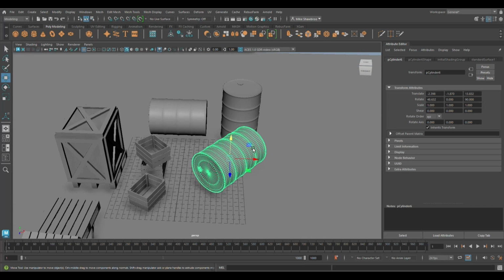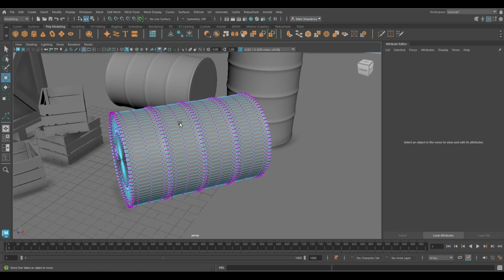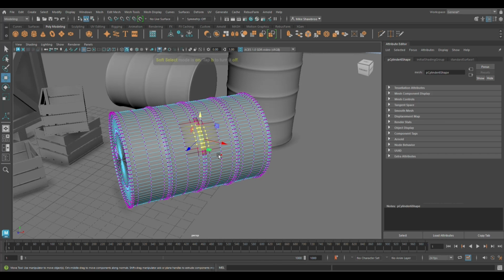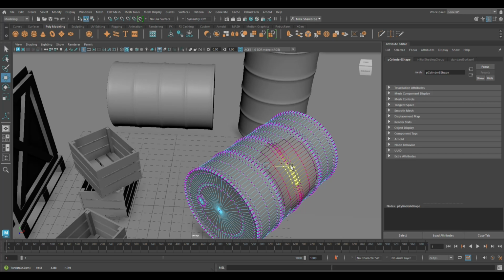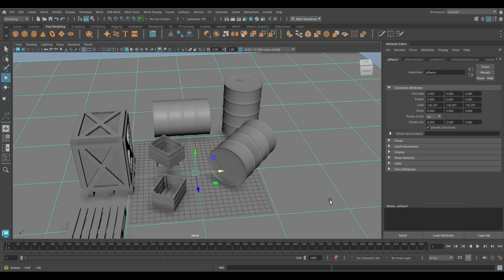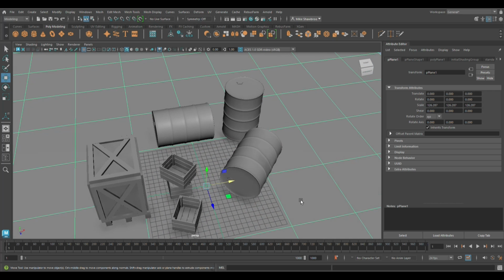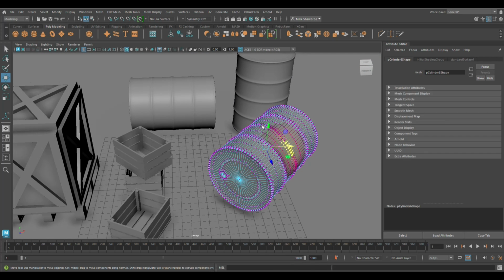So what we're going to do is right click, go to vertex, grab an area here, hit B on the keyboard, increase that area, and then we're going to kind of push it in and create a dent in it, as you can see right here. And you can make that worse if you want, especially by doing that on the top here.